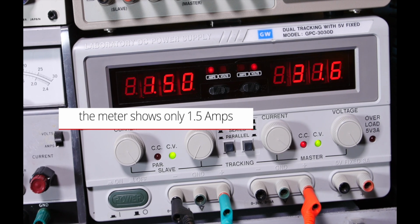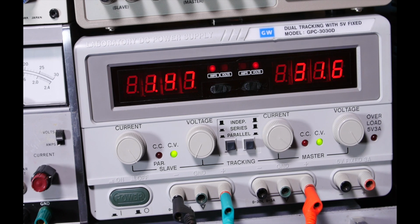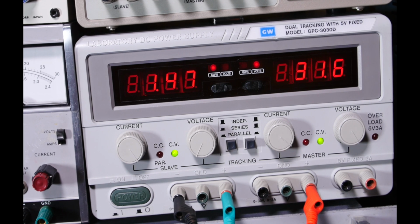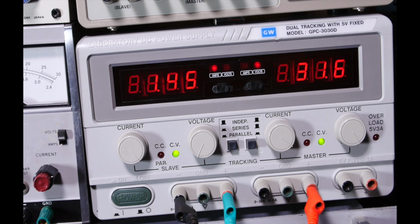Now if I lower the signal from my generator, right there, it turns off. But now watch what happens when I adjust the bias current. As soon as I start adjusting the bias current up a little bit, which helps take away the distortion, it comes back because of that. So that's why when I was adjusting the bias current I wasn't seeing any benefit: I was fixing one thing and hurting another.